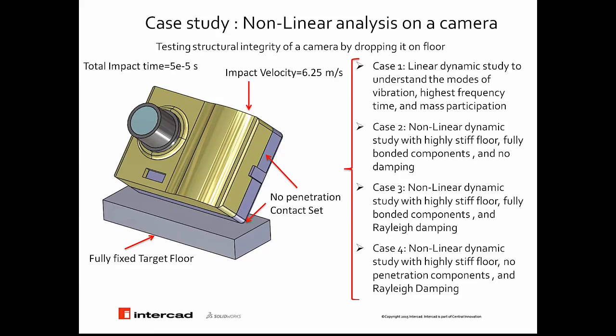We look at the highest frequency and mass participation. This is a very good guideline to understand the natural frequency and whether the dynamic study is applicable, and to find out the resolution of the time recording and the minimum time we have to solve the model.